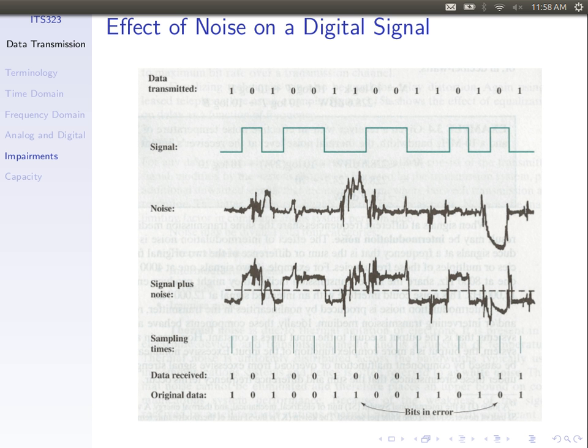You could do the opposite. Doesn't matter, as long as it's defined. This mapping must be defined, and I've defined it here. Bit 0, +1. Bit 1, -1. Defined by me. Therefore, the receiver assumes anything received between 0 and +1 is a bit 0, and between -1 and 0 is a bit 1.